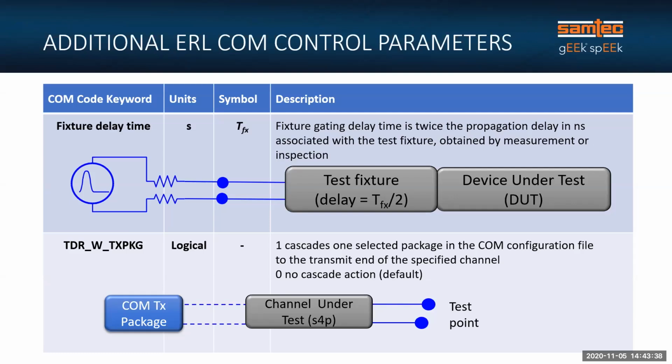But there are multiple de-embed methodologies, and coming up with a standard for that in a standards body, an IEEE standards body, with all the vested interests, is a non-starter. It isn't going to happen. So yes, you can de-embed the fixture yourself and then pass it through ERL. It's a perfectly valid way of doing it. There are standards that don't use the fixture.